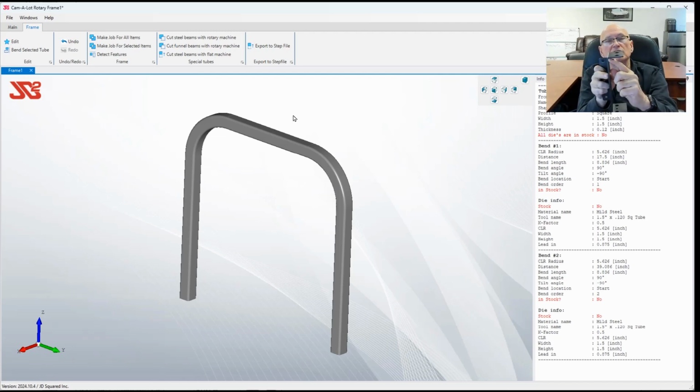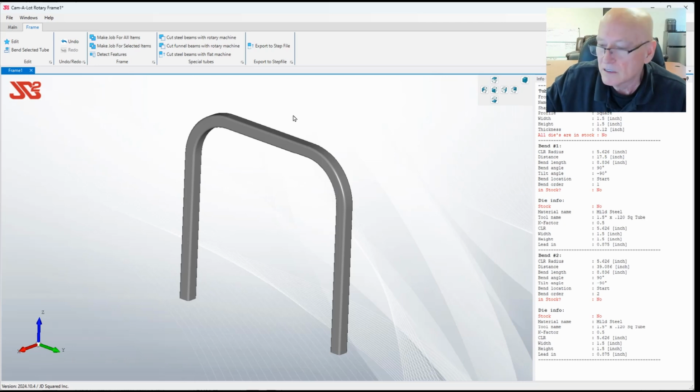We check on the inside, and on sheet metal you'll do it on the inside of the bend. On tubing and square tubing bends, you're going to check at the middle of the tubing, not the inside, not the outside. But on sheet metal, you're checking from the inside, and it would be off a little bit.